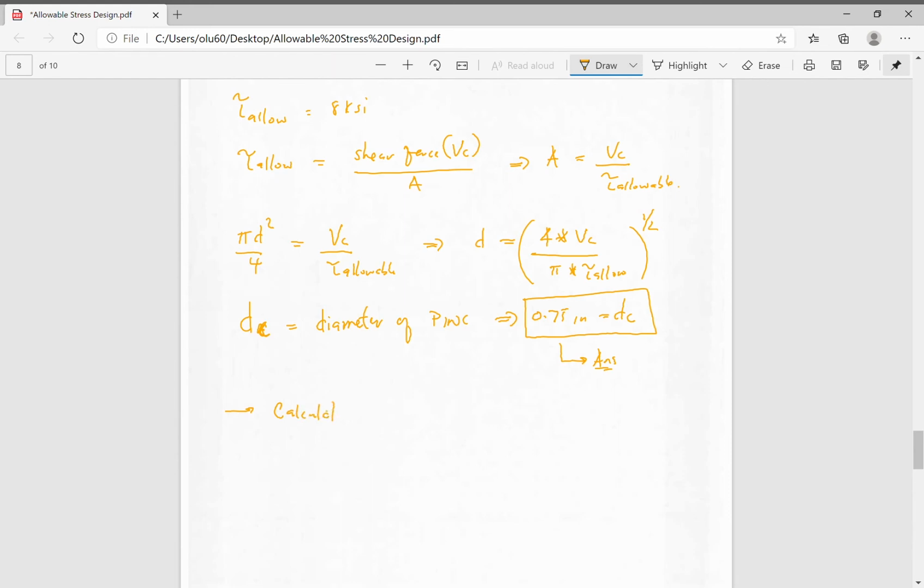So the takeaway really from this is the calculated diameters would prevent failure, at least from a mechanical standpoint. Again, we're not considering vibration, we're not considering any kind of atmospheric conditions like corrosion. We're not considering any kind of misuse of the part, but in terms of just the calculations and the size geometry that is needed for this intended application, we've satisfied that by this exercise. Okay. Now let's move on.